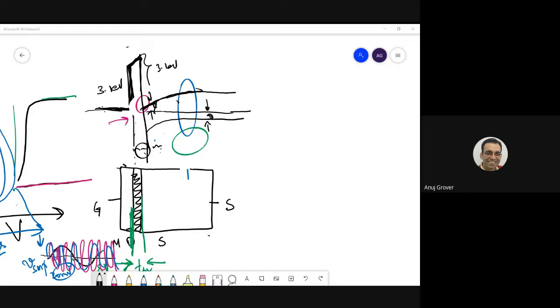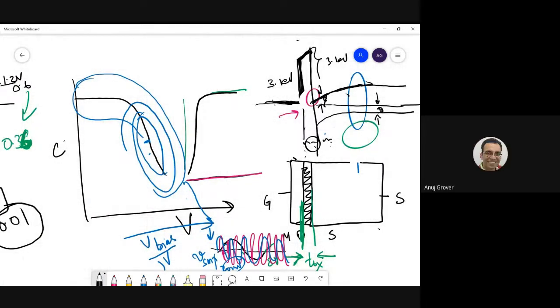If you want to use a MOS capacitor and somehow operate near the threshold voltage, then due to variations your capacitance will vary significantly. It could go low, it could go high, it could be anywhere. So you do not want to enter into this zone. Therefore, to characterize the MOS capacitor is very important.